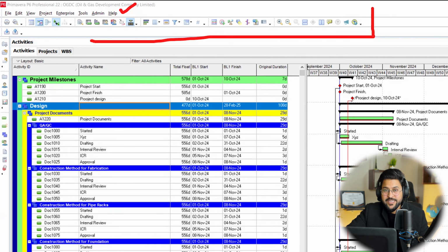I want this site manager not at the same level, I want this one under this project manager. I will move like this way, see. And EPC manager, okay. And I will move this one to this side, something like that, see. So that is how you can create your OBS.